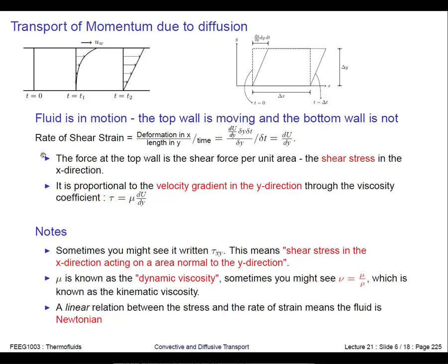the relationship between, if you like, the deformation of the fluid and the stress that is applied is the governing diffusion equation for momentum, and it's this equation down here. Okay, and just to point out that this du by dy is actually the rate at which you're straining the fluid or deforming it, or the rate of shear strain. So the rate of shear strain is the strain per unit time, and it's shear strain, so it's the deformation